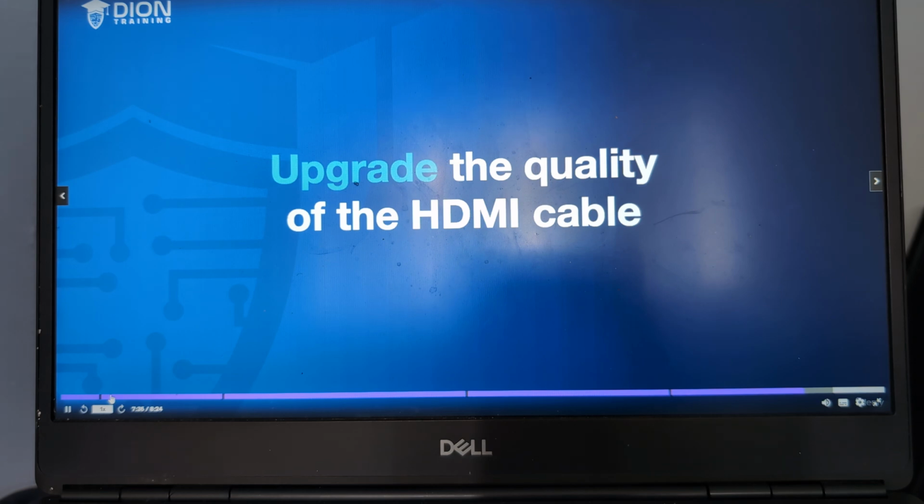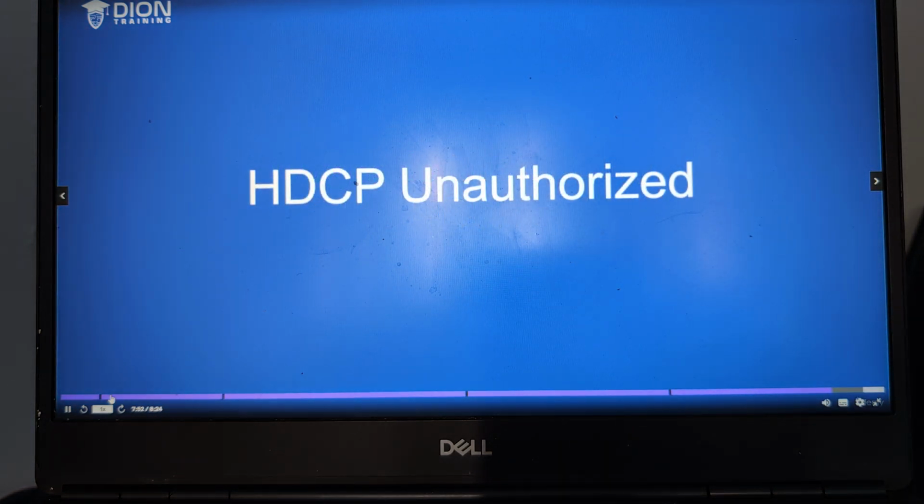during that handshaking process. Keep this in mind if you're working with any kind of set-top boxes, smart TV devices, or even game consoles, because all of these do use HDCP, and if that handshake doesn't occur properly, you're not going to be able to get it onto your display and be able to use those devices. And instead, you'll get an error saying HDCP error, the device you're trying to connect is not authorized for use on this system.